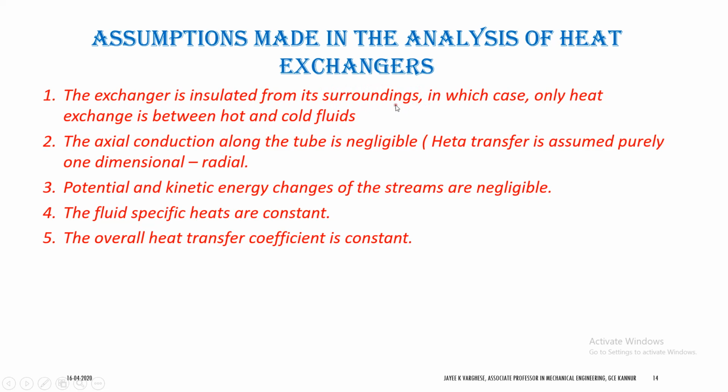This energy balance, which we will be making in all the cases for the derivation as well as for doing the calculations, is very important. Now another assumption is that the heat transfer is purely radial. We assume a one-dimensional heat transfer. So the axial conduction along the tube is negligible.